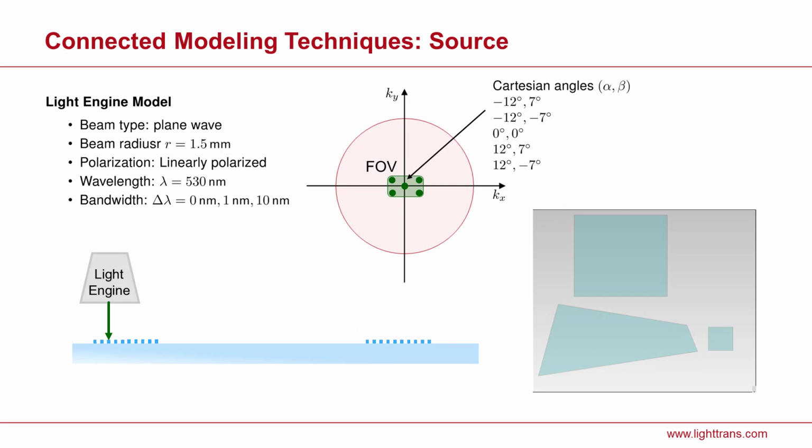And the digital overlay that we want to superimpose on the image of the real surroundings in the retina of the wearer is generated here in the light engine, where the light emitted by each pixel is collimated into a plane wave with a finite extension, that means with a given aperture, and a different direction of propagation, so that the position of the original pixel in the digital overlay is translated into a direction.